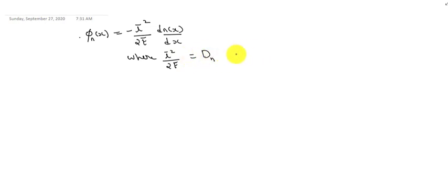This is known as the electron diffusion coefficient. So L bar is actually the differential mean free length and T bar is the mean free time related with the collision. So L bar square by 2 T bar is Dn. Dn is the electron diffusion coefficient.